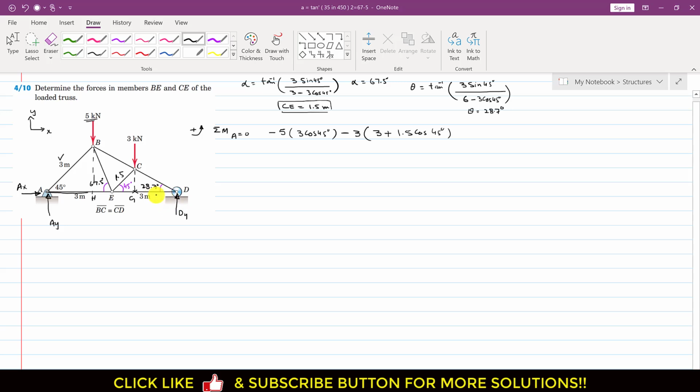So this Dy will produce a moment about A in the counterclockwise direction. I will write that as plus, and the perpendicular distance of this Dy from point A is 3 meters plus 3 meters, right? So this is 6 meters. So this is 6 Dy and this is equal to 0. When we solve this equation, the reaction at point D in the y direction equals 3.80 kilonewton.